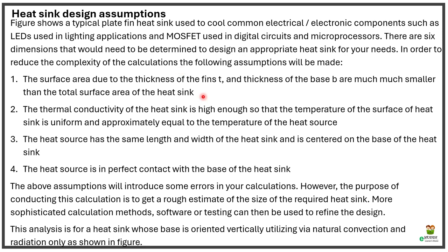In order to reduce the complexity of calculations, we have made some assumptions. The first assumption is the surface area due to thickness of the fins. So small t, that we are considering the thickness of the fins, and the thickness of the base, B, are much smaller than the total surface area of the heat sink.